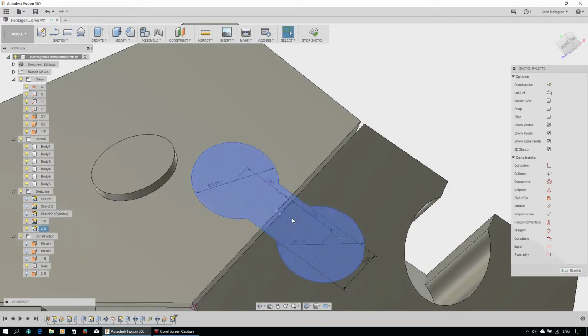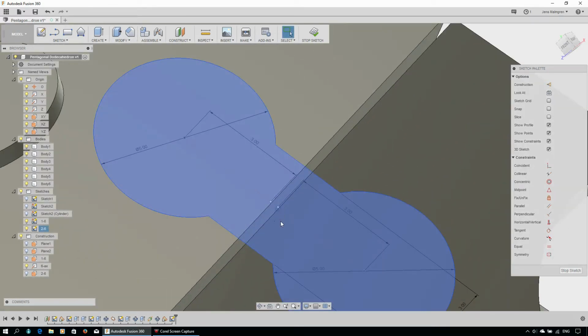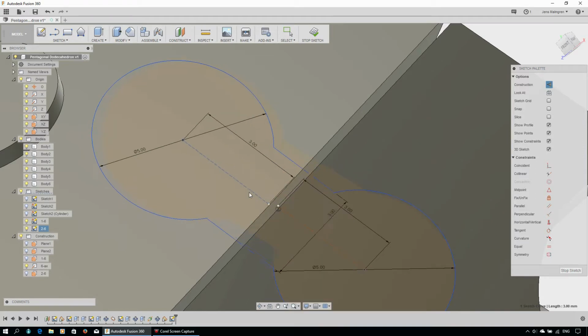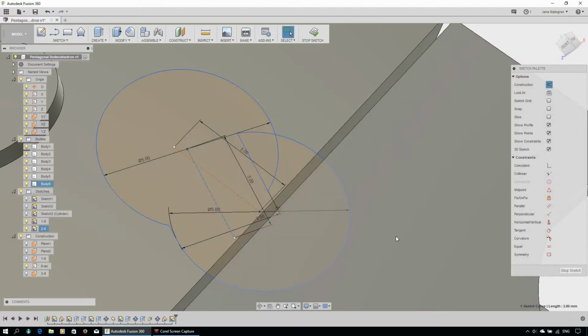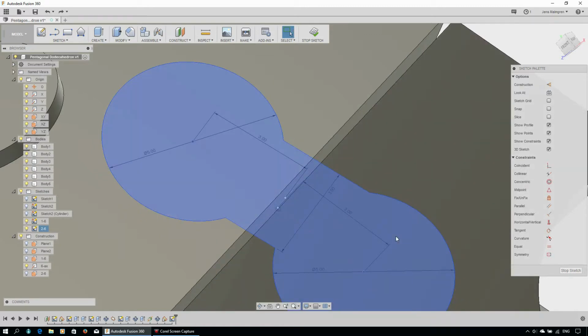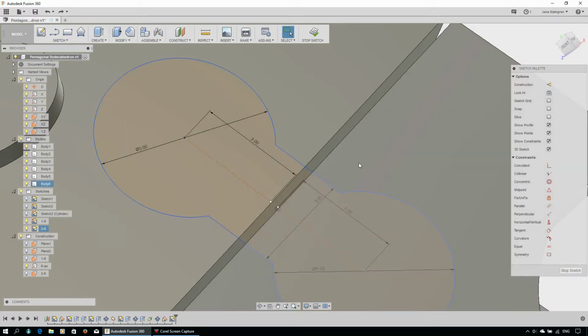However, if I were supposed to, for example, move little points here of this sketch to get it to the absolutely correct spots, then we can try that now for a moment. So I start dragging here. As you can see, my drawing disintegrates, and this is because I'm missing important constraints here. So I press Ctrl Z to undo this. And let's talk about the constraints instead.